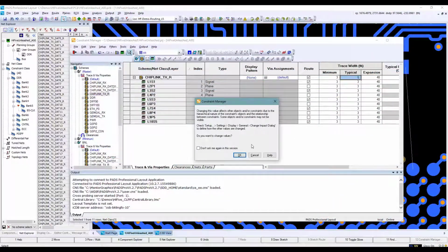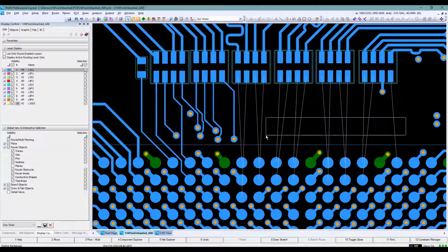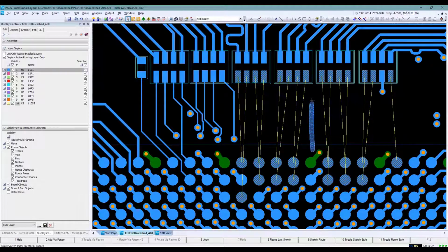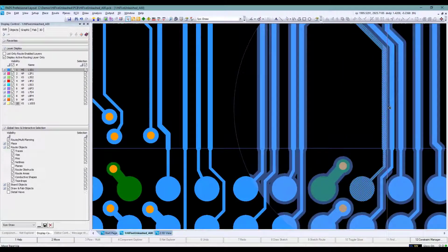The integration of different circuit technologies many times requires different rules for areas of the board. Professional allows us to create area rules that can be placed on these different circuits, automatically taking care of our spacing and trace requirements when routing between these different circuits.